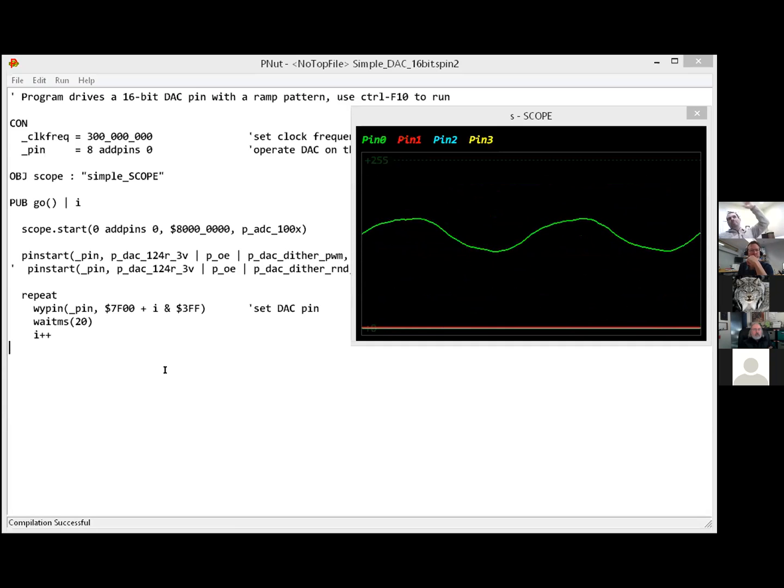So do people have any questions? You guys understand what's happening here? Why you see a little lump occurring and then it goes all the way up and then it flattens? Whenever it flattens, it's hit an integral 8-bit DAC value. And then as it starts to lump up, it's because it's going a little bit beyond that towards the next level. And then eventually you get little nodes pointing down and then it levels out. So this is the best linearity you can get out of these DACs.